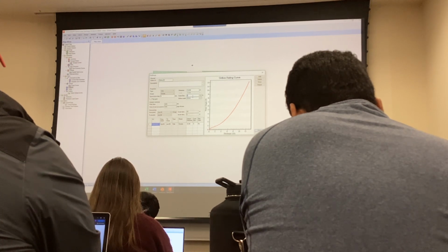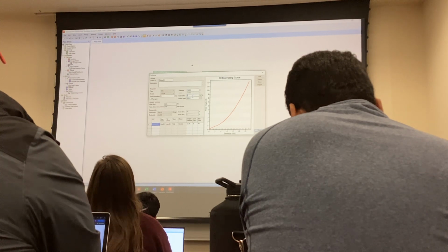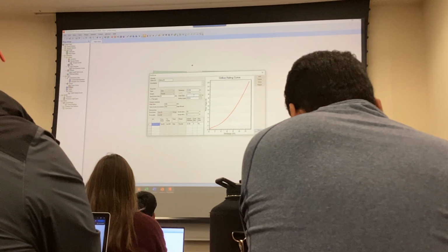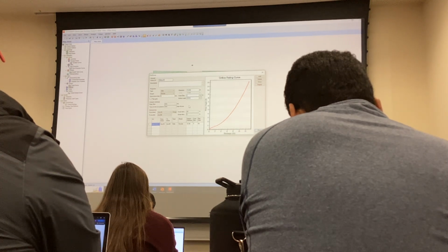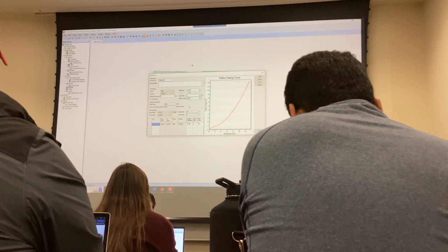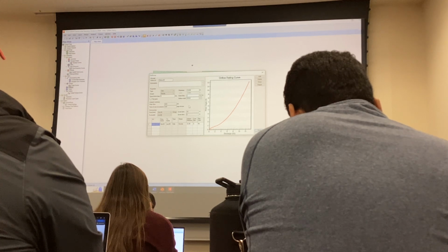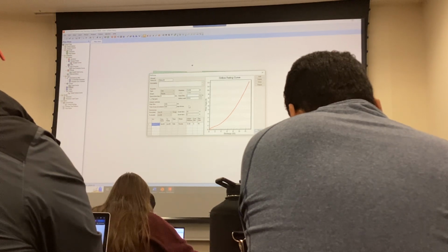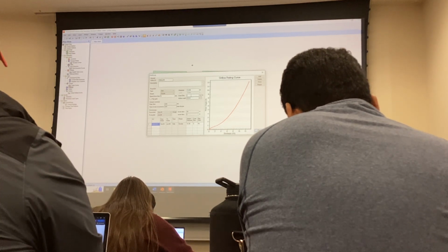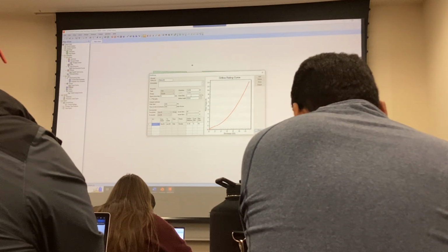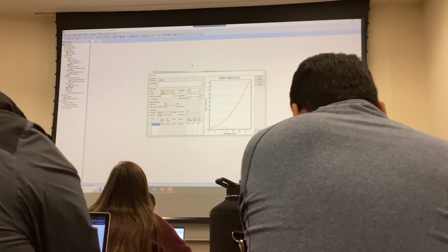So hypothetically, this needs to be known before you actually put it in, because you need to match the elevation with the elevation of your detention inlet and the top of the detention basin, and make sure that it's between those minimum and maximum elevations that you want. Okay, so in this case, my minimum is 10, right?